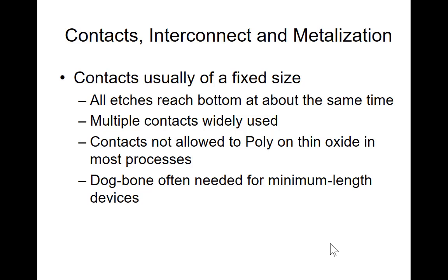After you go to metal 1, from metal 1, if you need to send it a long distance, you may need to go to metal 2, and metal 3, and metal 4, metal 5, etc. When you go from one metal layer to another metal layer, at the intersection, this is metal 1, this is metal 2. They are at different heights on different floors. If you think of a building, all the silicon is on the ground floor, and then your metal 1 is on the first floor, and the metal 2 is your second floor, etc. So they are at a different height.